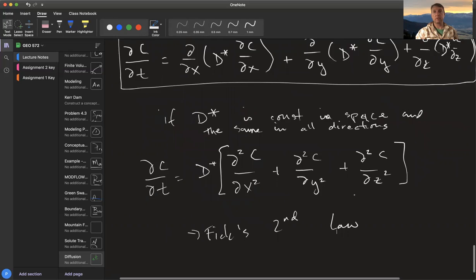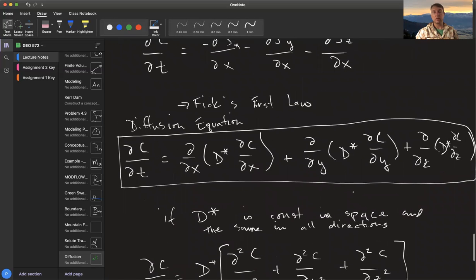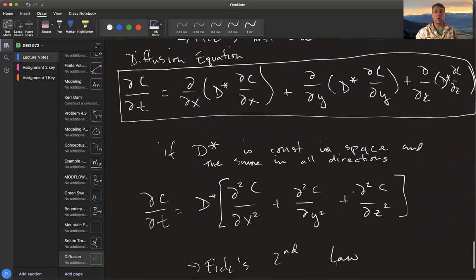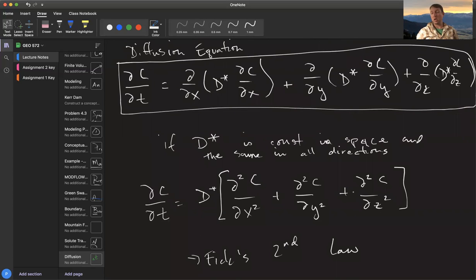All right, so this is the diffusion equation. So here's the cool thing. All of our groundwater flow solutions, for instance, the instantaneous step change in head, we had an analytical solution for that. Well, it'll work for the diffusion equation. So here we might have an instantaneous step change in concentration, all right? And we can look at how that concentration change propagates diffusively through a media.